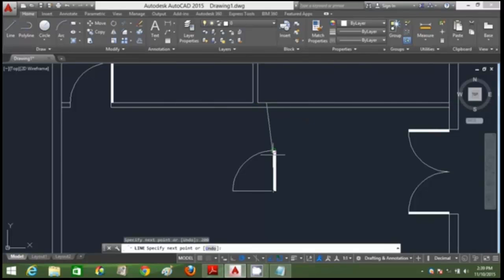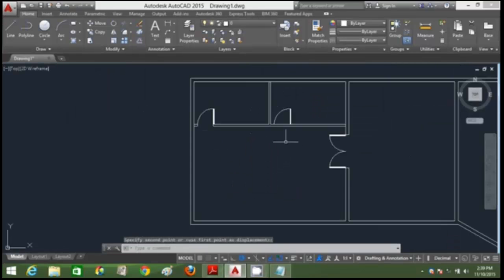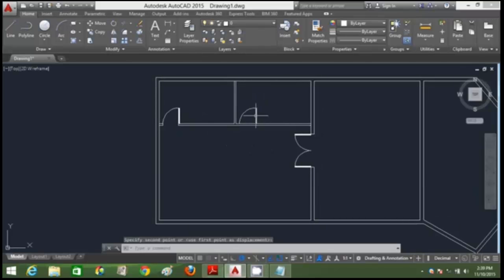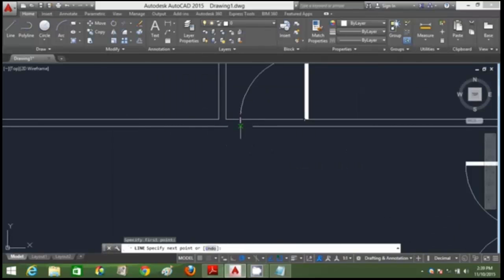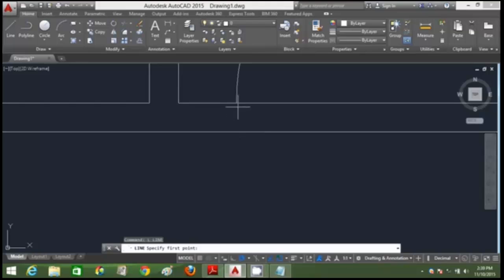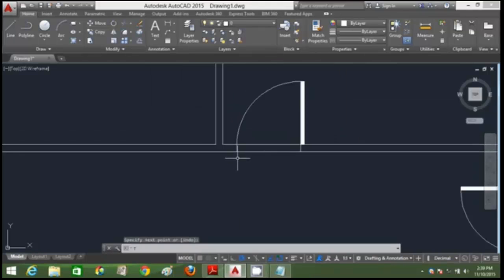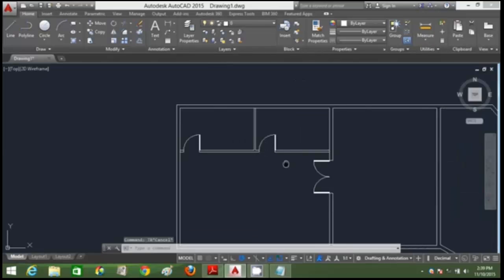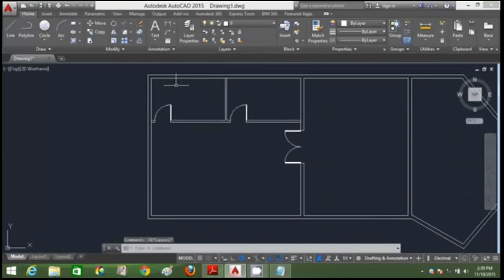Mark a reference line by 200 mm and move this towards that point on that reference line. We actually have to set the boundary of the door first, and trim it out. Delete this one first. Make sure the line goes straight using your polar tracking. Select the overlap line. Trim out the unwanted portions. Alright, so we got that ready.